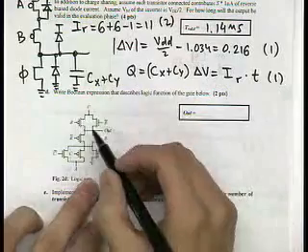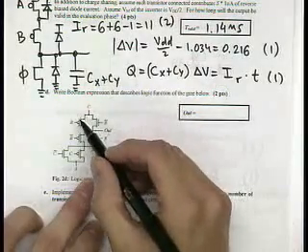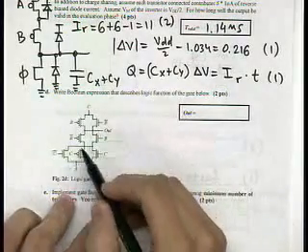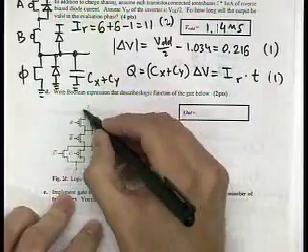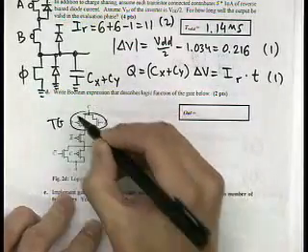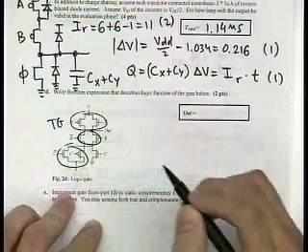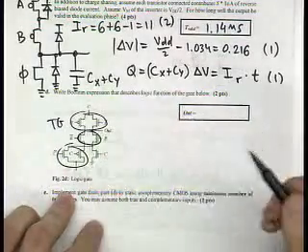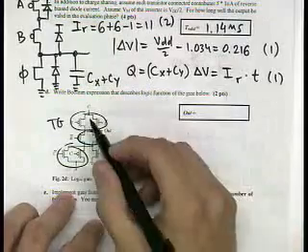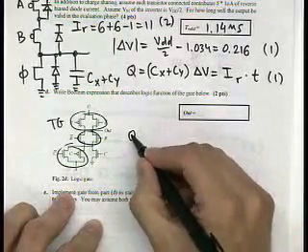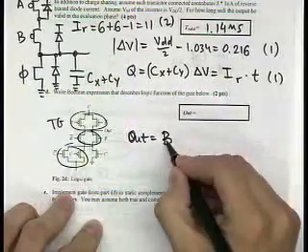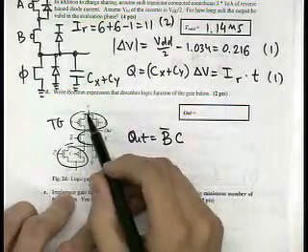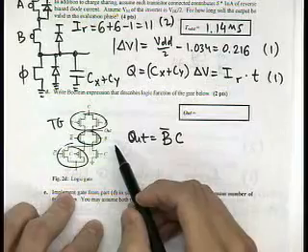So what we observe is that this is a transmission gate, this is another transmission gate, and the third transmission gate. These are the simple observations that we make. So we analyze this in block form. The first transmission gate is turned on when B bar is 1, and if C is equal to 1, then the output is equal to 1 as well.